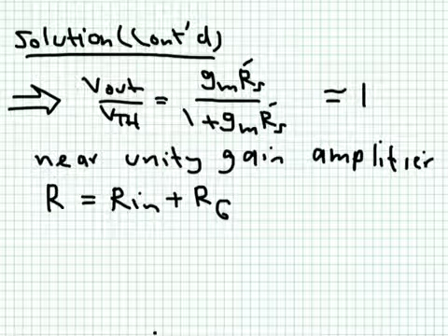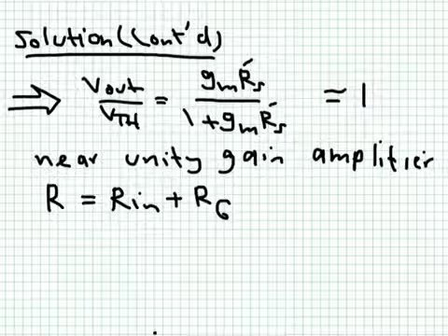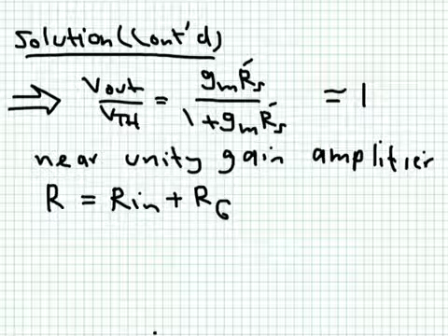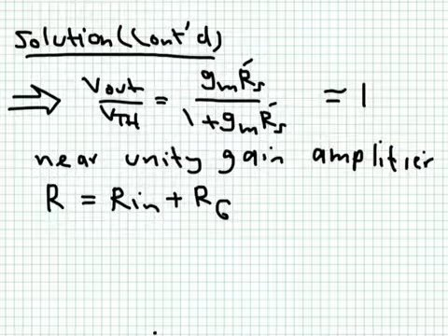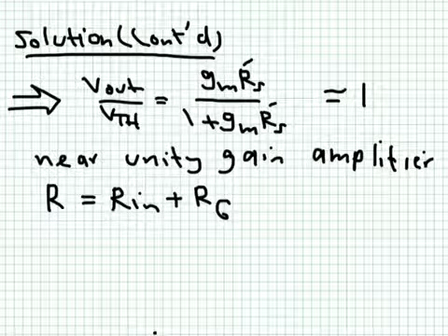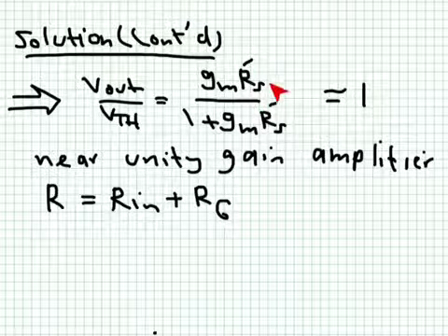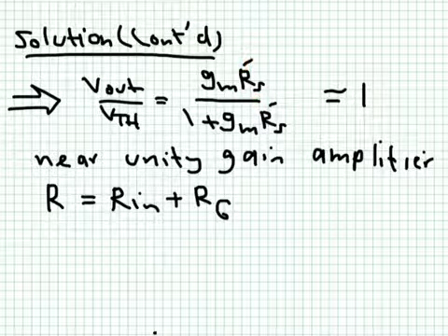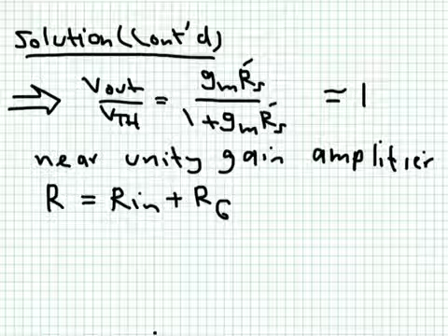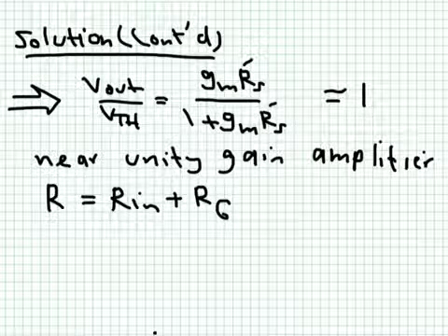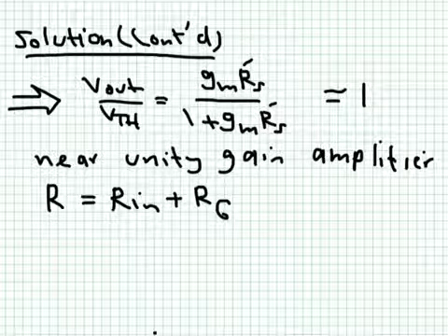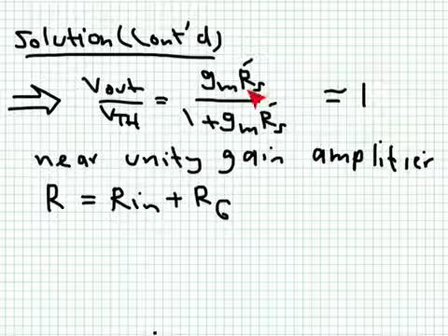So this is what I got. I removed VGS and replaced it in terms of V Thevenin, and when I do that, I get this expression here, which is exactly what I mentioned in the beginning. And keep in mind, RS dash is the total resistance connected between the source and the ground. In our case, we had two parallel resistances, one connected to the source and one as a load resistor, and their net combination is what gave me RS dash.